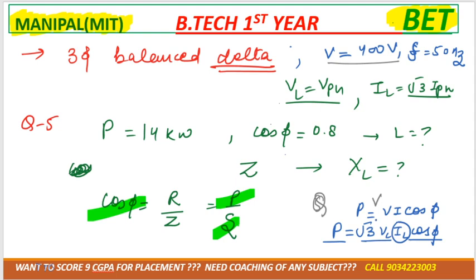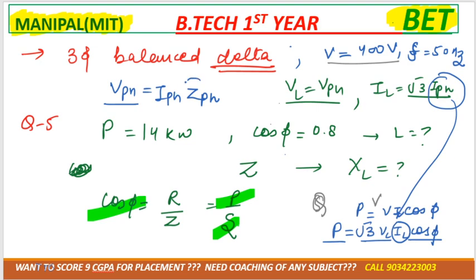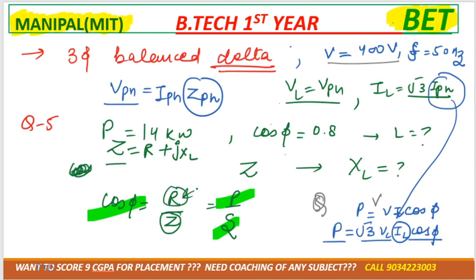We can get I, and after getting I, we'll have the formula VPH is equal to IPH into ZPH. VPH we know, IPH we can get by IL, we can get ZPH. Okay, after getting ZPH, we can get Z is equal to R plus JXL. Z we know, R we can get from here, we can get XL, right?